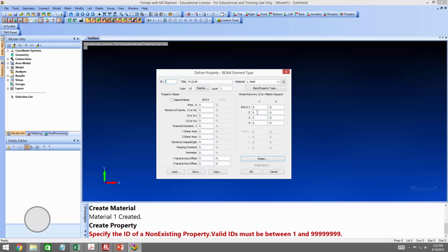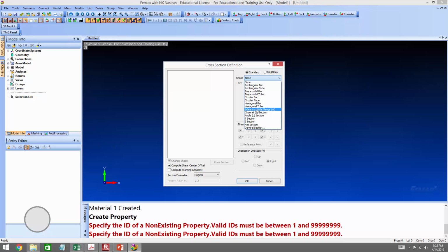So I'm going to create a beam, and then if you recall, I'm going to go down and create a shape. Remember, we're going to do a wide flange section, right? And help me out. I think we had a height of, I think it was like 11.9, and our width was like 8.01. It was like 0.515 for the top and bottom. Was anybody remembering these? Anybody write these down? Oh, that'll be right. I think that was 0.515, 0.515, and 0.295.